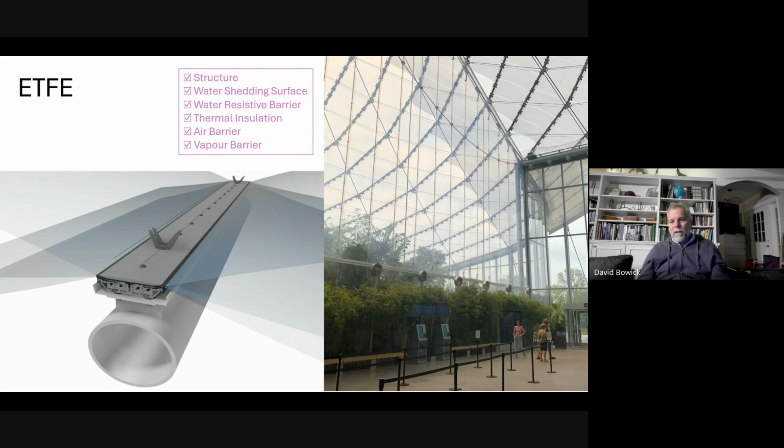The image on the right is from Assiniboine. These are our partitions. So these are single layer ETFE partitions. Those vertical cables are every 1.5 meters. We put the partition above, so the bottom 3 meters is vision glass, because it's super clear.